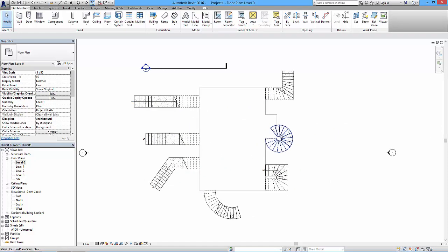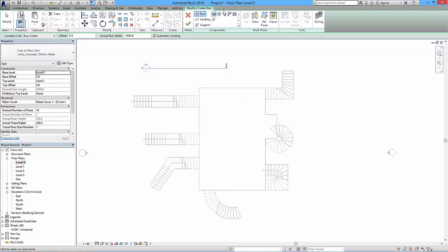If we look at this type and this type and this type and this type, we go to stair and we'll look at the L-shaped winders first. So click on that, and again these follow basically the rules that we've got there. Level 0 to level 1, no offsets, and the same sort of information. And this one just comes in as a complete looking thing.